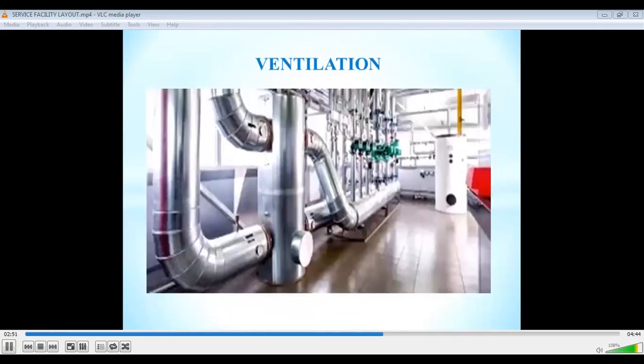Ventilation is the dynamic parameter that complements the concept of air space. For a given number of workers, the smaller the work premises, the more ventilation there should be. Ventilation differs from air circulation. It replaces contaminated air by fresh air, whereas air circulation merely moves the air without renewing it. Where the air temperature and humidity are high, merely circulating the air is not only ineffective but also increases heat absorption. Ventilation disperses the heat generated by machines and people at work. Adequate ventilation should be looked upon as an important factor in maintaining the workers' health and productivity.